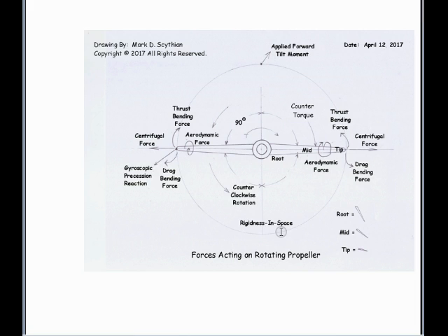So that's the advantage of having contra-rotating propellers, is that you can cancel out the precession and the torque. But do know that if you have large span contra-rotating propellers, the rigidness in space gets a little intense, especially at higher RPMs. And pilots do report having a little hard time actually getting a response out of the controls for maximum control authority. So, once you get level, you can drop your power or your RPM relatively lower, because you have two sources of propulsion.